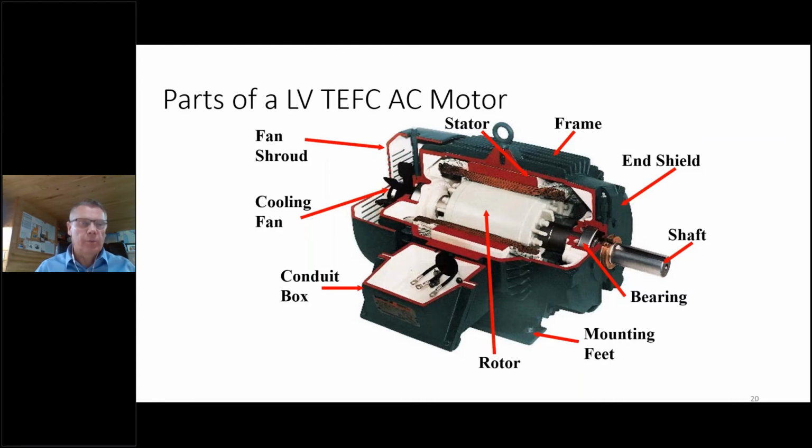I'm not sure if you're familiar with the term IP. So this would be your typical IP54/IP55. I haven't put a bullet there, but if you look at the shaft, you'll see a brass fitting. That's your Inpro seal. And as I mentioned before, with TEFC, you have a shaft-mounted fan. In this case, it shows sealed leads, which is all enhanced protection.